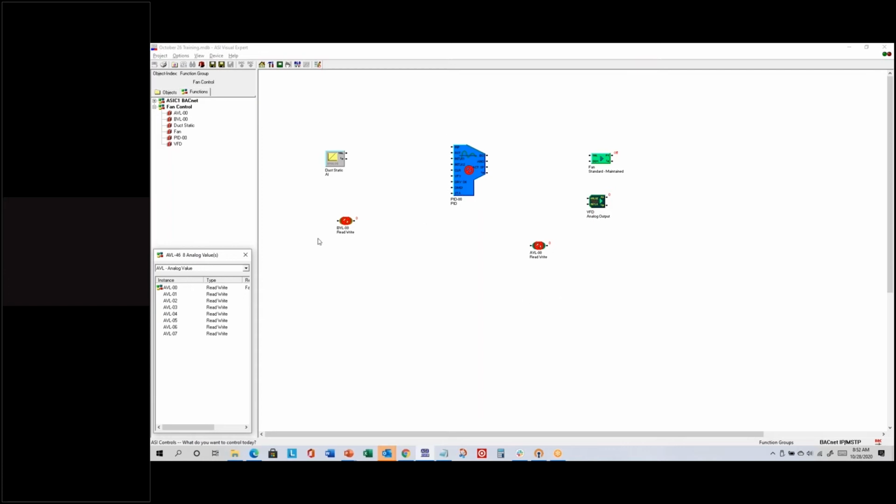Okay, so you can see that some of the icons have the red circle with a slash, so we want to enable those. You could go to each one individually and do a right-click enable. What I tend to do is select a group of them and enable them all together. There are different ways to do multi-select. The way I usually do it is to just draw a rectangle around all of the ones I want. If you select one that's already enabled, that's okay. Once you have multiple icons selected, you can right-click on any one of the icons and select enable, and they all become enabled.